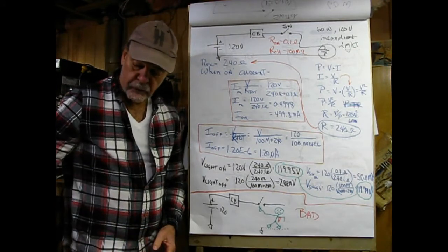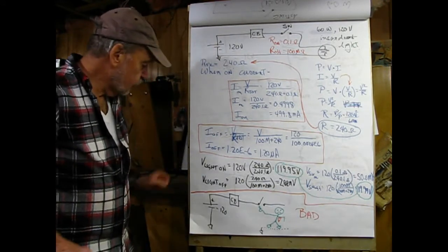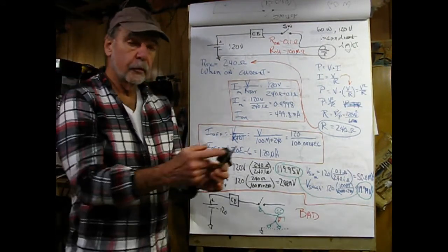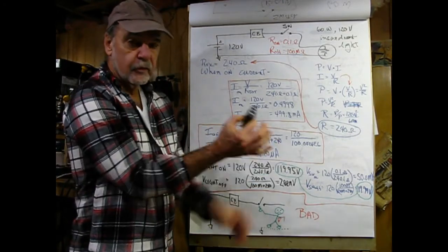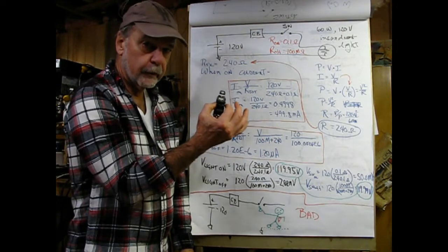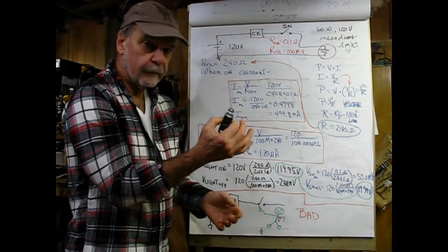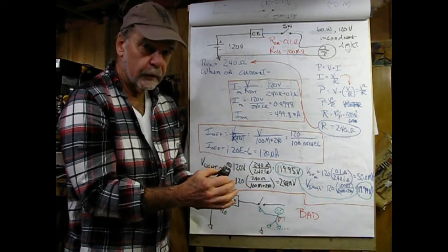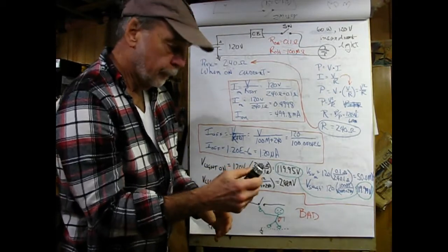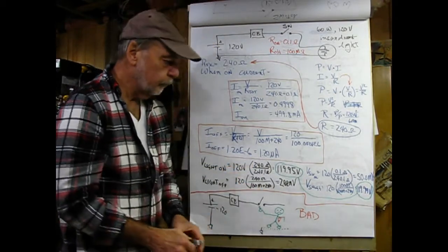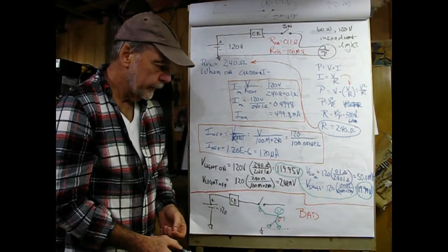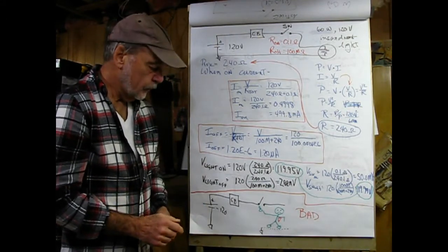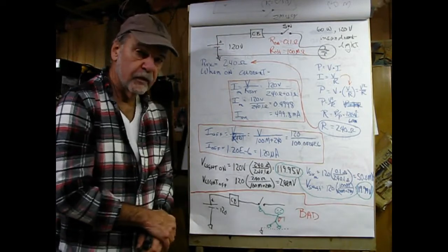Now, what that means in reality is that if the circuit's turned off, and here are the two terminals on the switch, if I were to take my fingers and touch them like this, I would be across 119.99 volts, and I most certainly would feel it, in a relatively unpleasant way. I've had a number of shocks. I never like them.